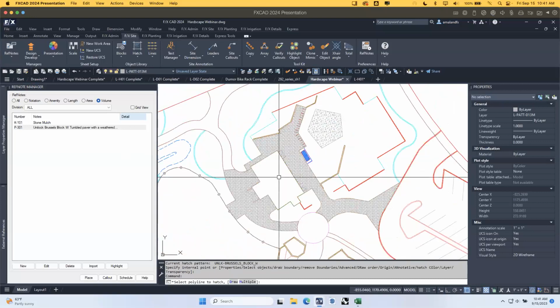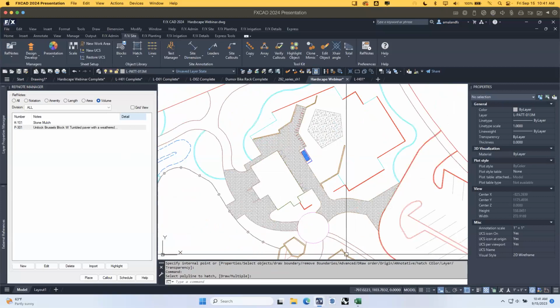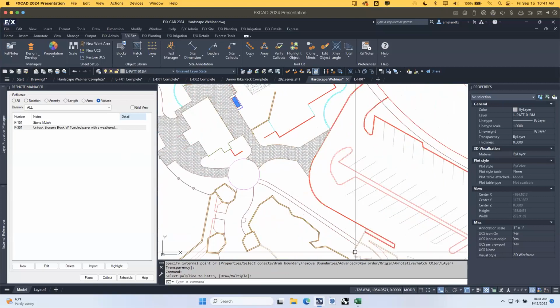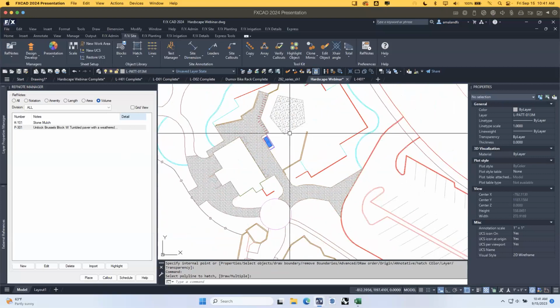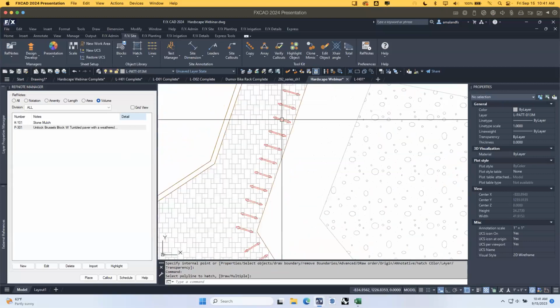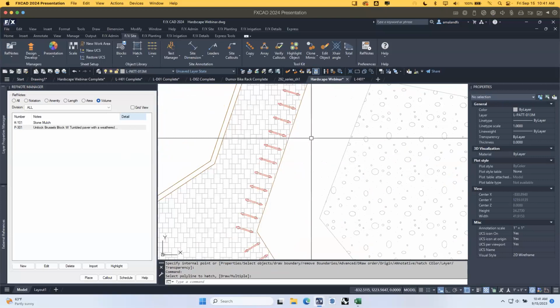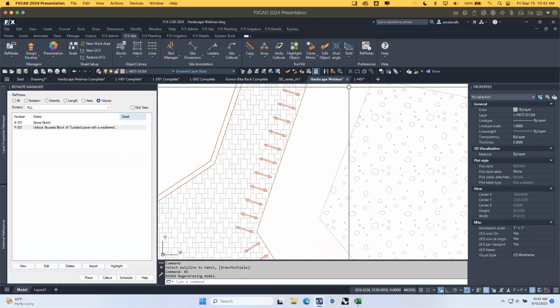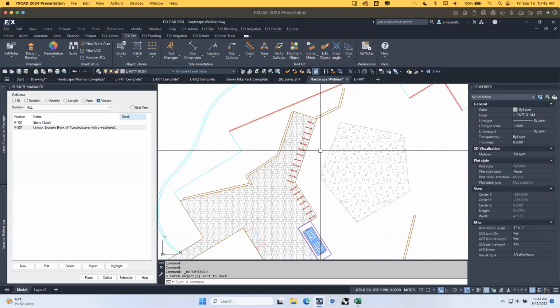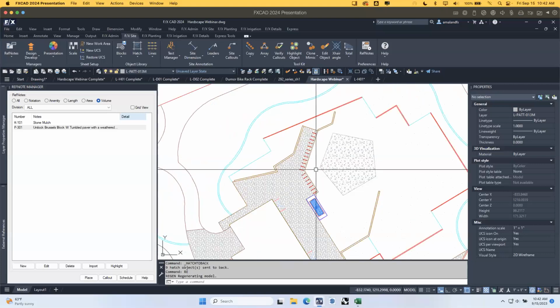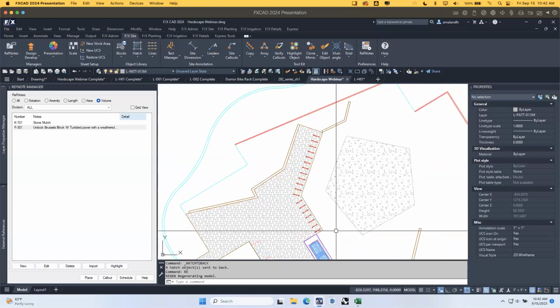So that kind of just highlights the importance of making sure your polylines are properly closed off. I hadn't totally closed off that polyline yet, but good CAD drafting is always a necessity at any level. If you get this issue where the hatches are somewhat going over, it's usually a display issue and you just have to type RE and they'll go behind. But if they don't for some reason, you can always use HatchToBack, which is a great CAD command to send all of those hatches off to the back. There we go. Now they're looking pretty.